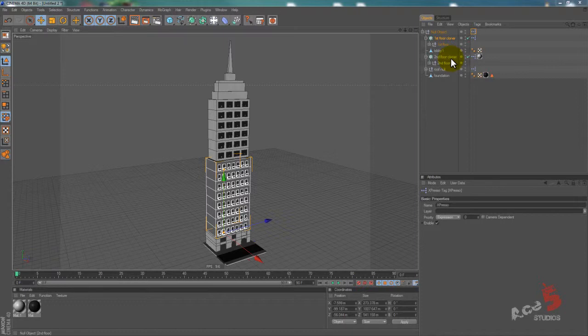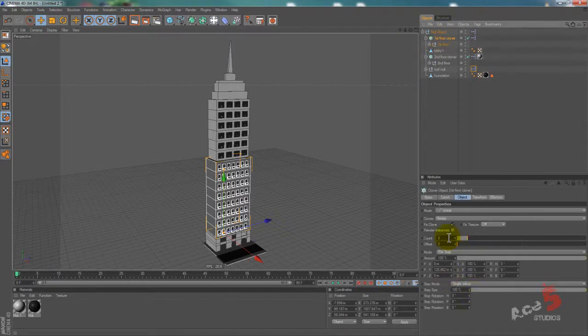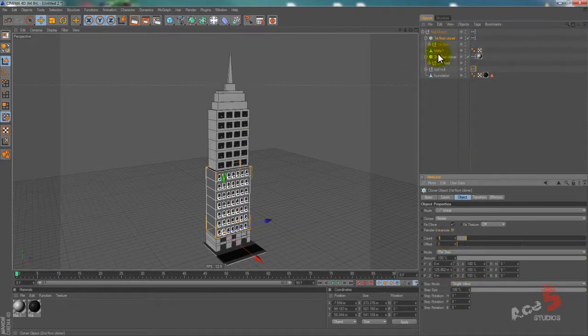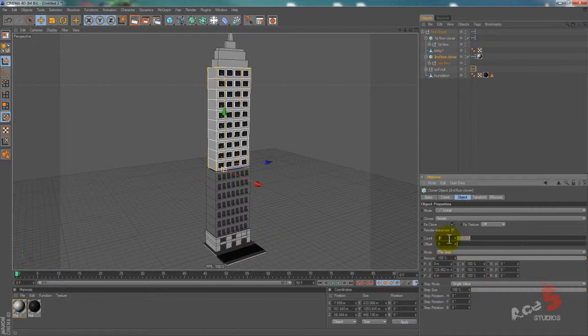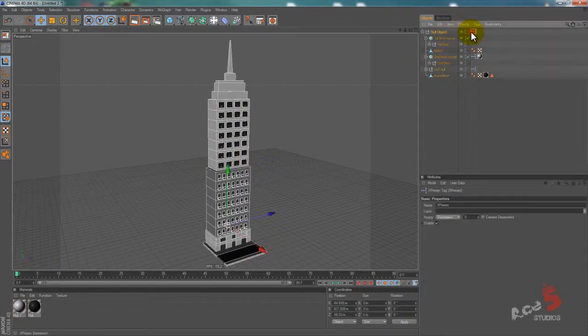So what you want is you want it to go through these, calculate where they are, and then with this Xpresso check where the roof is meant to be, and then you won't get that lag on it. Just make sure again, see, all smooth. So it's important to consider where your Xpresso tag is, or where your calculations are. Same thing that happens with constraint tags.